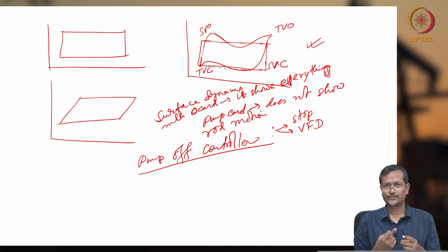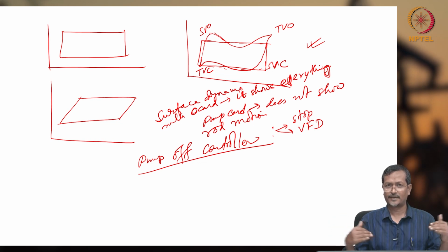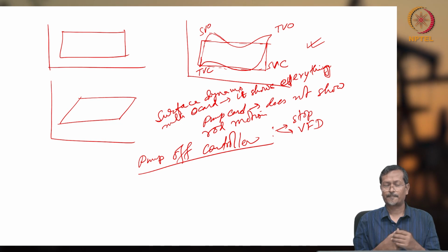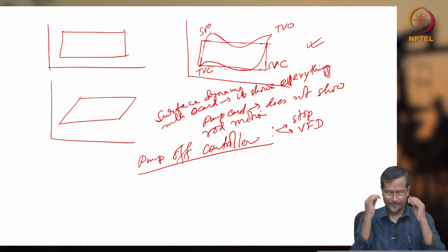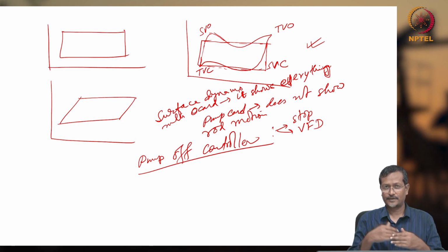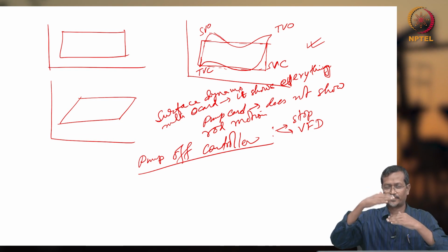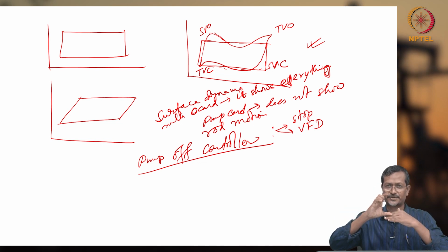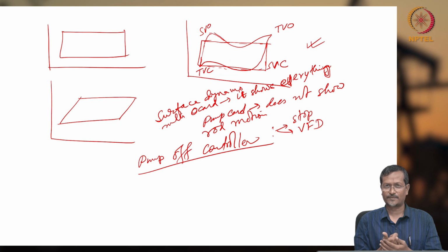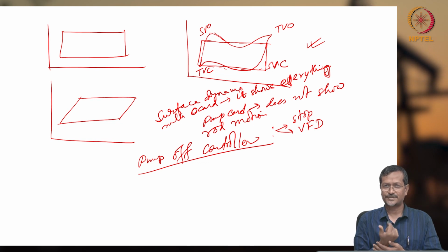So there are two issues. One issue is that very little fluid is coming. Another thing is that you are actually creating two-phase flow. When fluid enters your pumping area, you are reducing pressure. When the plunger is moving up in the cylinder, you are reducing pressure. Reducing pressure means if there is any dissolved gas, it can go out. If it is creating two-phase flow, you can get gas.